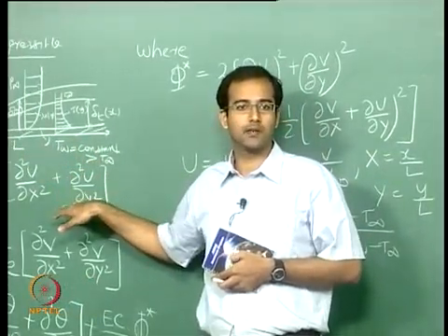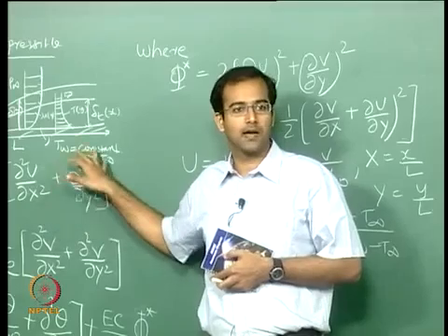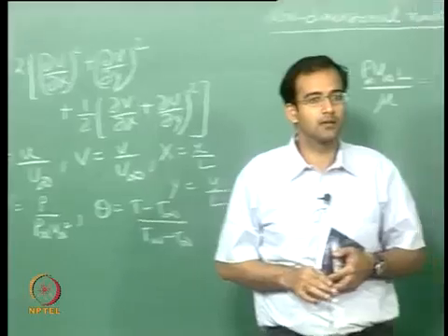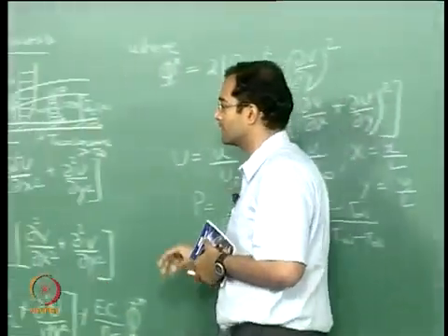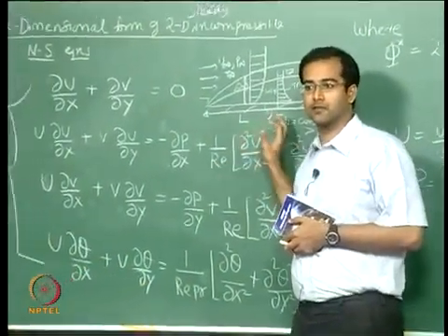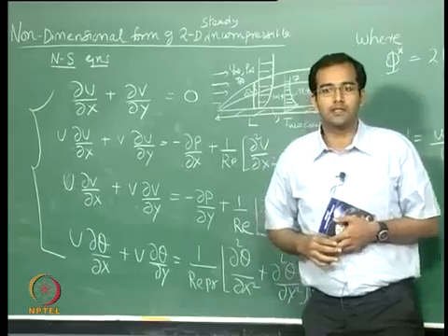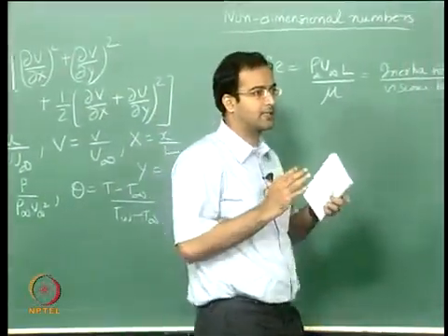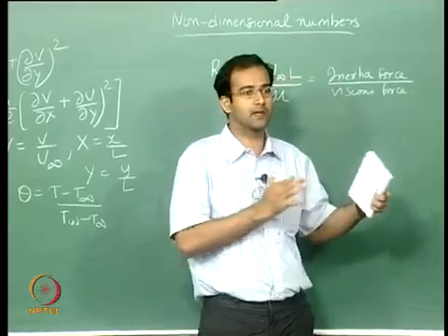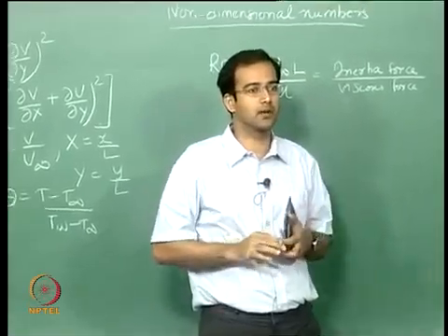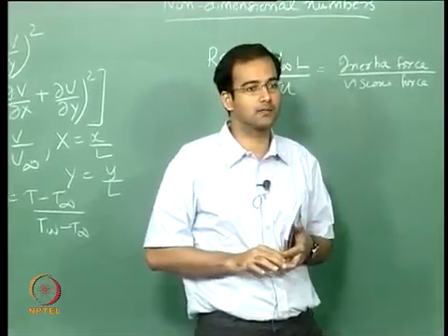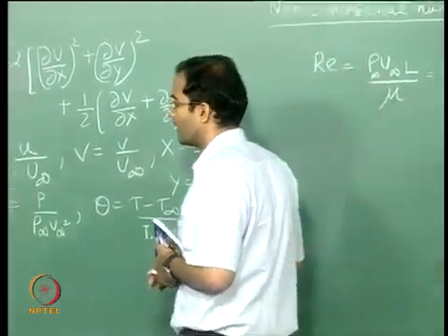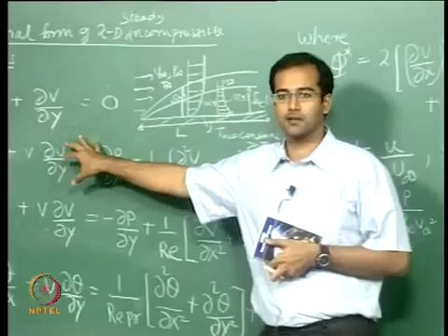Under the limit of small Reynolds numbers, you have a viscous diffusion dominant flow. At very high Reynolds numbers, you can neglect the diffusion terms compared to the inertial terms. Of course, you want to operate in a regime where you are not too extreme, not going towards a very small or very high Reynolds number. So in those practical situations, you have both these terms being significant.